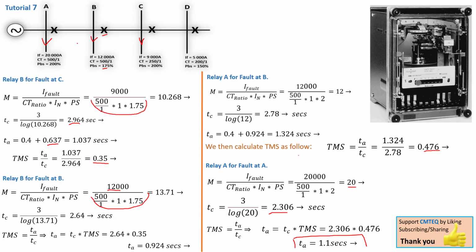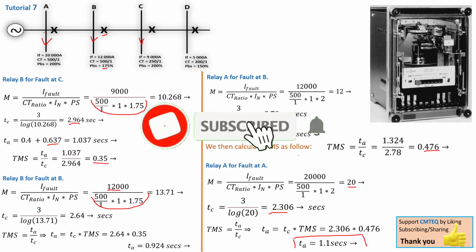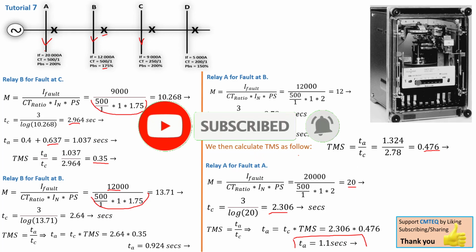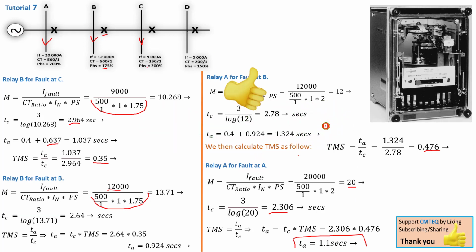And you can never have a situation where you have a higher fault current on bus bar B and a smaller fault current on bus bar A. It can never be, because this is a downstream flow. So this is a power supply, your substation or your power plant generator. The power is flowing this way, and based on your per unit system, you're not going to have the same level of fault on the first bus bar up to the last bus bar, because there will be some voltage drop and impedance in your system that's going to limit the current.